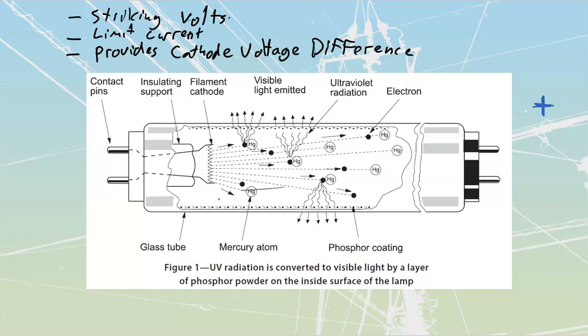You do reduce your lamp light by switching them to frequency. Operating with the wrong type of ballast, obviously, you're going to have wrong values of voltage, either too high or too low, which is going to result in too much current, or wrong heater cathode voltage, etc. Using excessive supply voltage, too many volts, obviously, once again, a problem. And then losing cathode preheat during startup.